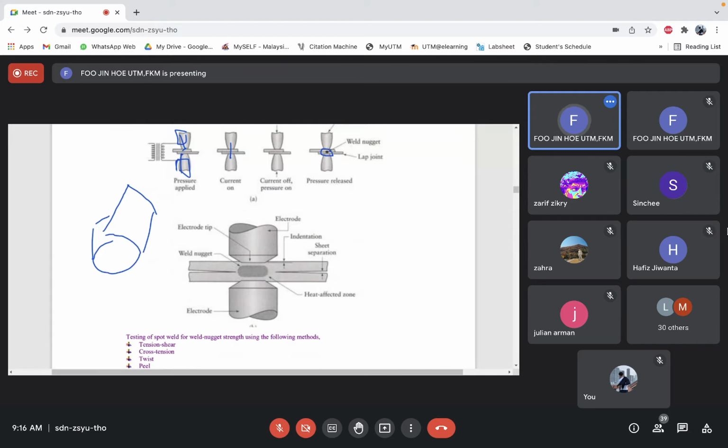In the end, I wish to weld these two areas. However, you know that this is for drinks, right? So the drink is something like this, and if I only weld a weld nugget, something like this, it's not going to hold the water. The water is going to leak through the non-welded area. So the best thing is that I weld through this whole thing here.